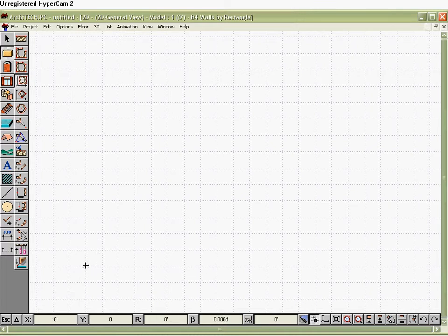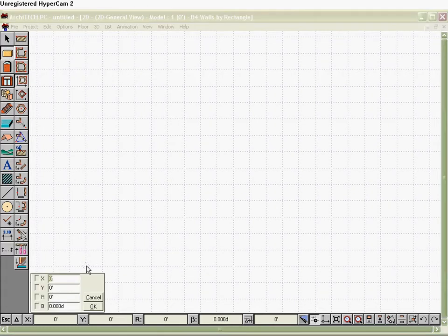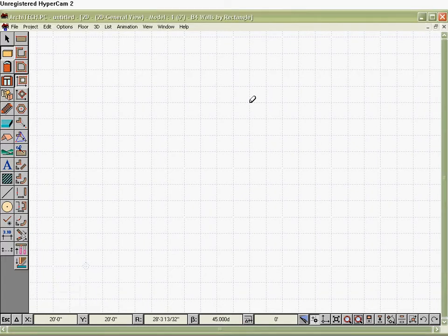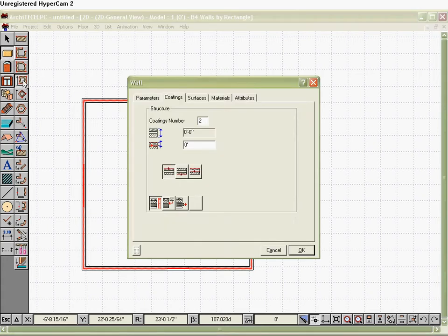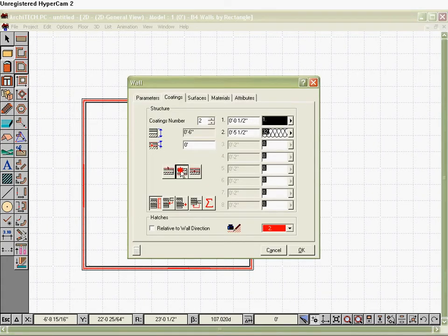Now we're going to do it correctly. First, left click. Now hit Shift Tab. Type in 20, Tab, 20. Hit the Enter key. Hit the space bar. And there's a 20 by 20 building, but actually it's 21 by 21. What I said originally about this being perhaps the inappropriate key, that's the one we're going to want. So we're going to choose this reference line position rather than that one.